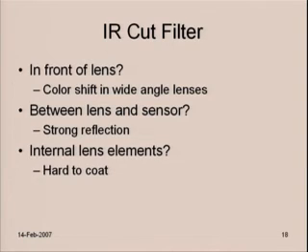The trouble here is that coating these glasses can be difficult, and there are yield losses associated with that, and so it drives up the cost of making the lens. But it has been done, and I actually think that most consumer point-and-shoot cameras use this technique to reduce flare. Many also have an IR cut filter in the back. There's a lot of variation in that space.